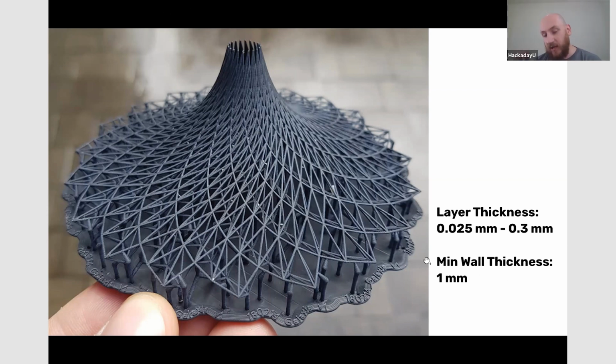And with any 3D printing process, you're looking at what is the maximum dimensions of the print area, what is the layer thickness. And the more layers you have in 3D printing, the better resolution the 3D print is going to be, but the longer it's going to take to 3D print, because the machine is going to make a two-dimensional print of every single layer. And if you want a quarter of the thickness to be more accurate, that's 4 times the print time. And that's a decision one needs to make.